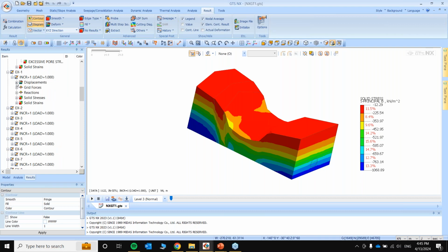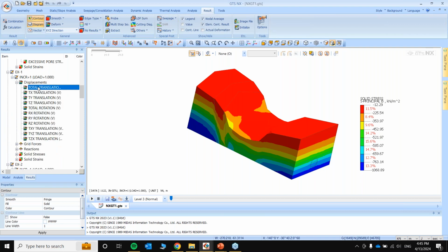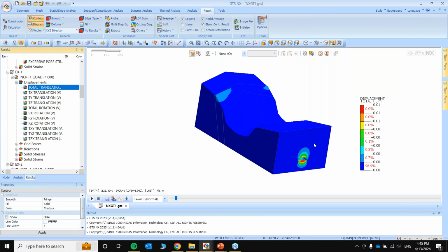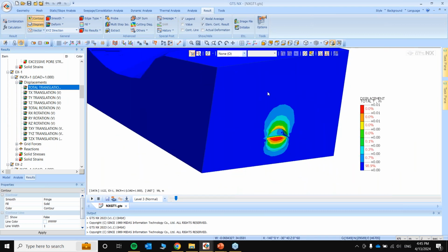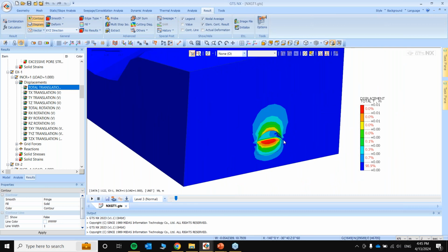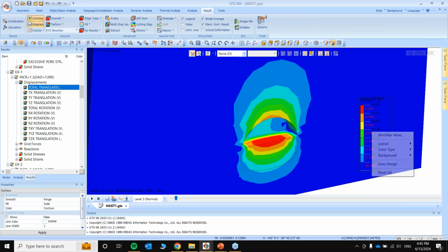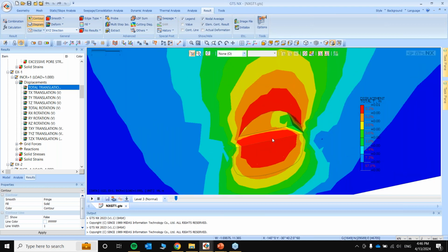So our first excavation. First excavation means first heading. This is where the stresses get redistributed. That's why you can expect a bit of heaving in there.